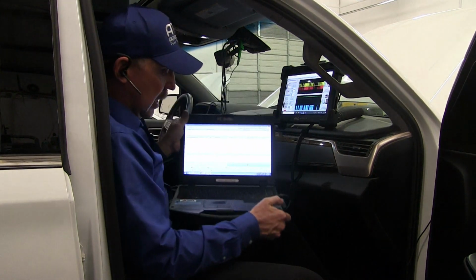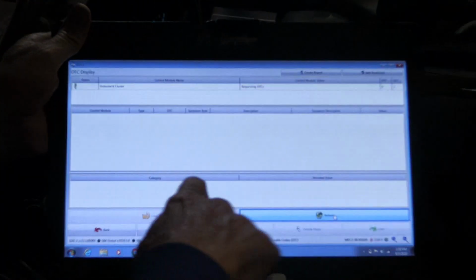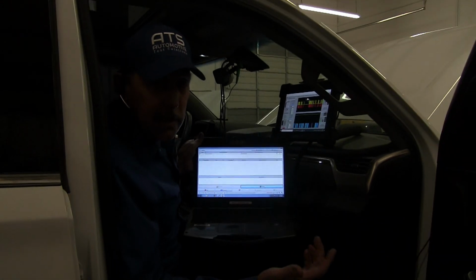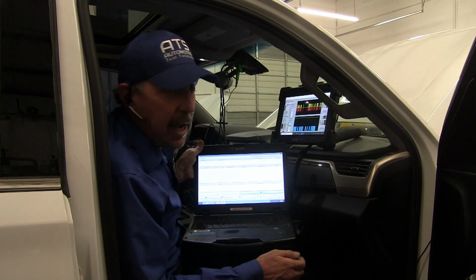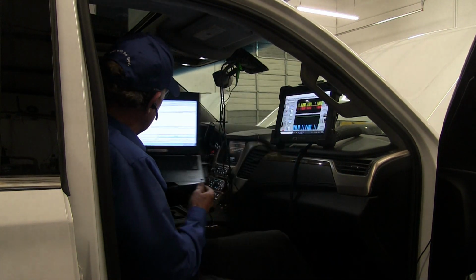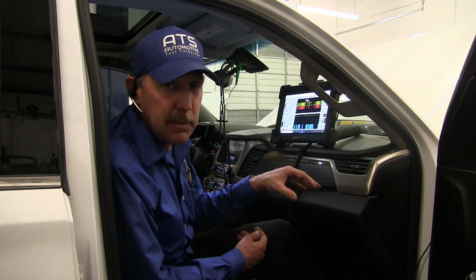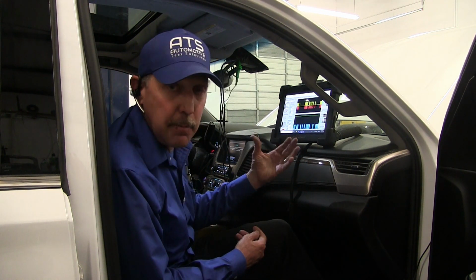So it's bridged outside, and we can prove that this fixed the car, and the car's been running for a while now. We can look at our scan tool and refresh it, and we can see we're not setting codes. The reason that we were setting codes is because we had no GM LAN communications to the forward camera, and it can't transmit its data on these LAN packets.